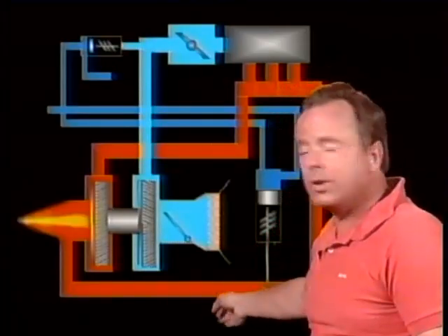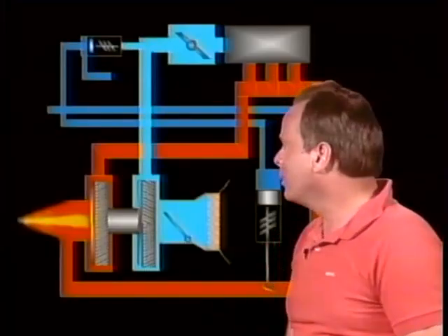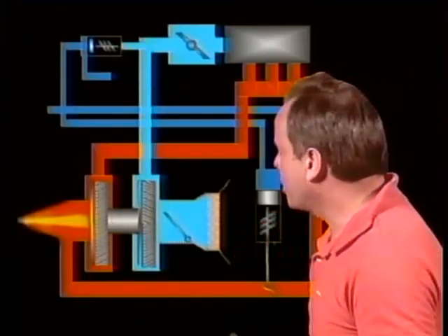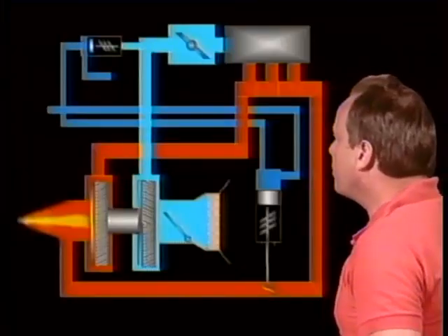That's what a density controller does. It opens the wastegate if you start to overboost the aircraft. All right, the differential pressure controller is an elegant device, and it's what we used to have in a Cessna 340 that had a turbocharged system. Let's take a look at the differential pressure controller.